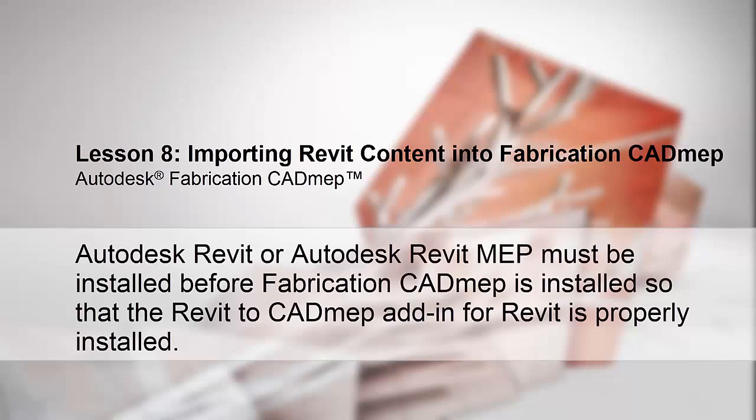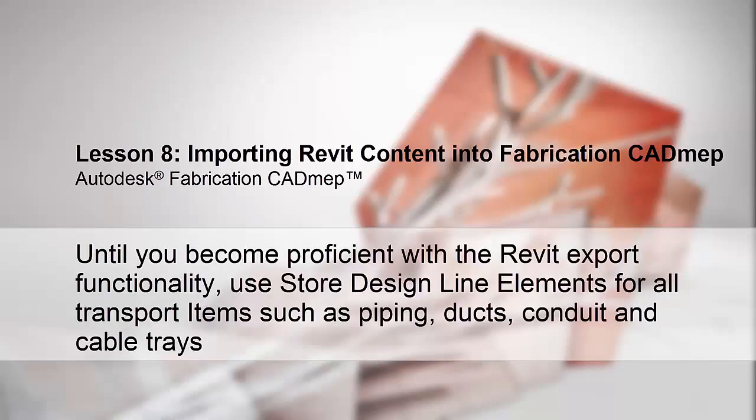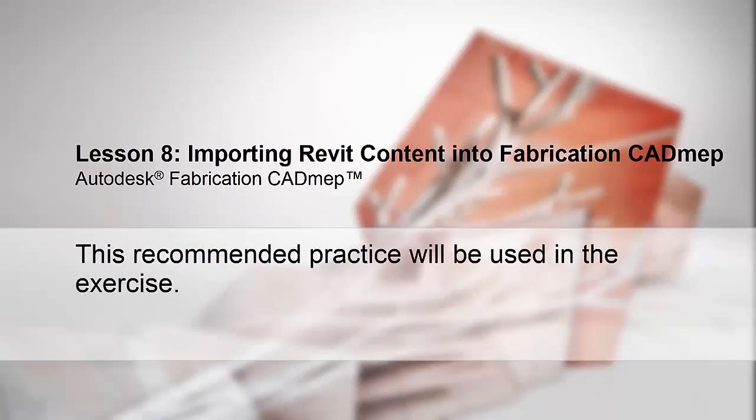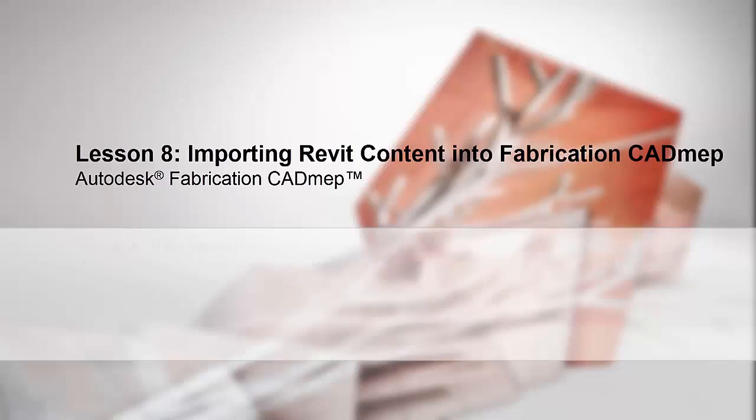Autodesk Revit or Autodesk Revit MEP must be installed before Fabrication CADmep is installed so that the Revit to CADmep add-in for Revit is properly installed. Until you become proficient with the Revit export functionality, use Store Design Line Elements for all transport items such as piping, ducts, conduit, and cable trays, and use Store Graphic Elements for supply and demand equipment such as pumps, lavatories, diffusers, panels, and light fixtures. This recommended practice will be used in the exercise.